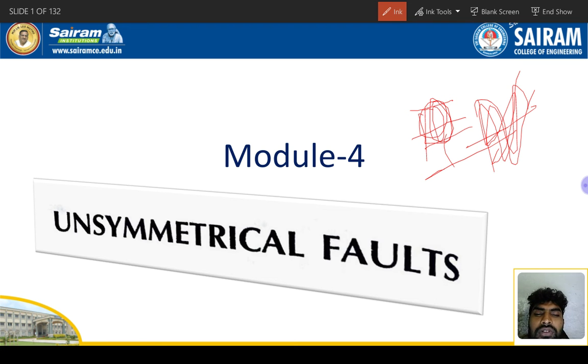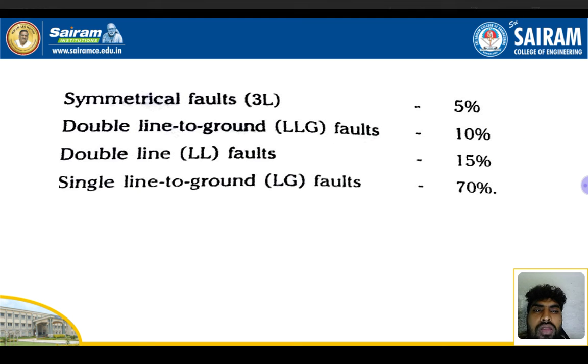In the previous class we discussed symmetrical components and symmetrical faults, in terms of phase components: positive sequence, negative sequence, zero sequence. Here also, for the unsymmetrical fault, we will get positive sequence, negative sequence and zero sequence. They usually give one single line diagram. We have to draw the reactance diagram. After that, we have to determine the fault. They'll mention the fault location, so we need to calculate. So let's move on to the topic.